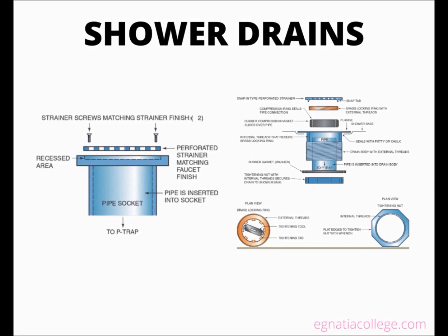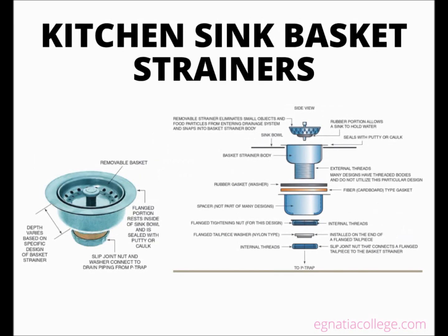If a tile shower is installed on a concrete floor, codes typically do not require a safety pan. A one-piece shower drain can be installed there. A pre-molded shower base has a multi-piece shower drain that is installed by securing it to the base. A one-piece shower unit uses the same type of drain as a pre-molded base.